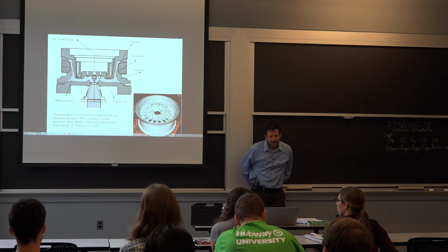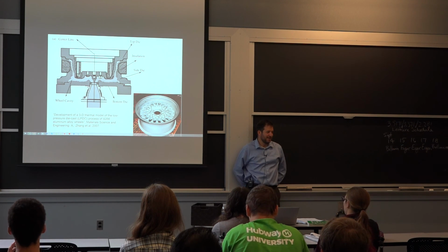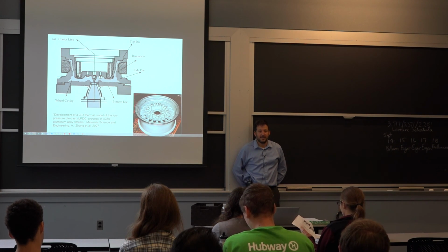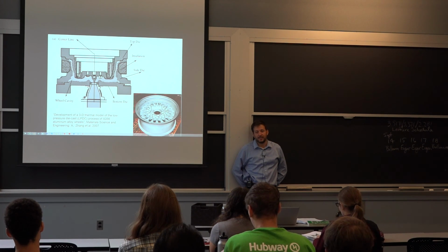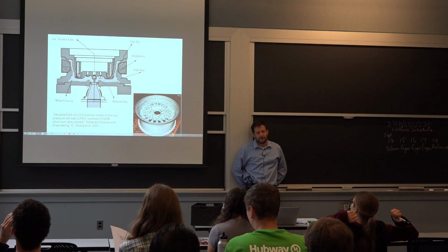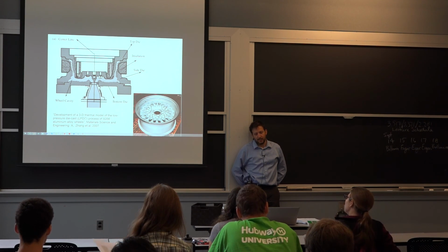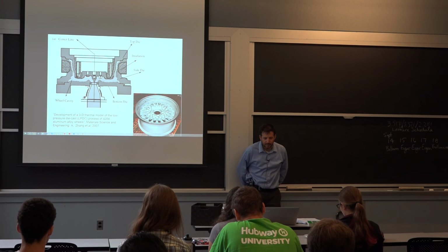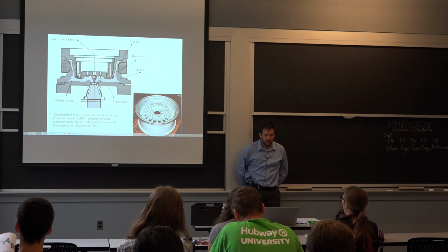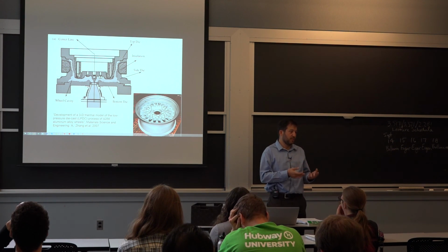Is it worth it? Yeah. I mean, what else could we do with this wheel? You could forge it to get some good properties. Machining it is a lot of loss. It's not impossible, but it's a lot of loss of material. So I think that's one example. They've used different kinds of alloys for doing this, but in the end, you do need to lower the properties as opposed to if it was forged.